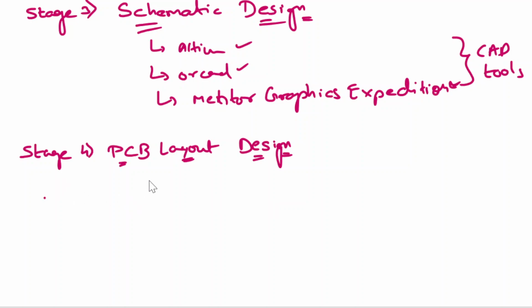So the first thing is what? We have to contact the PCB fabricator regarding whether they are meeting our requirement specifications, design specifications, such as stack-up. We would have finalized how many layers the PCB should have. Then we are moving into characteristic impedance for high-speed signals and traces, and then we are moving to the next actions. I have a query here.